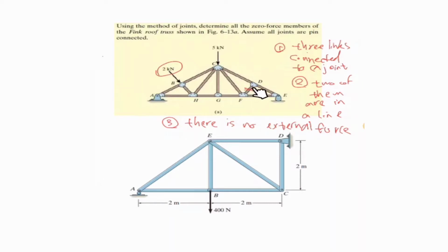Let's get back here. There is nothing in front of this. Then, if this one applies some force, this point starts to move in this direction. But here, we need a link to fight this, to keep this point in a static equilibrium condition, meaning that we have exactly 2 kilonewtons in this link to cancel out the effect of this and keep this point in its position. Okay, this is not a zero force member.